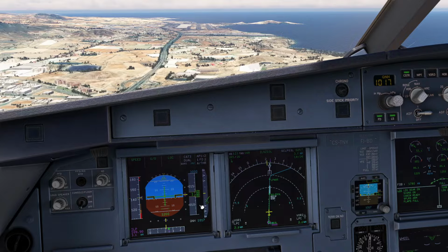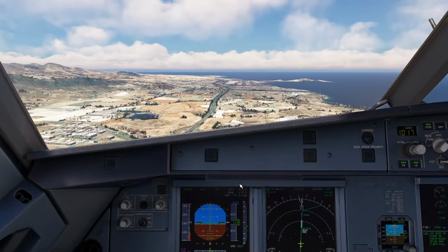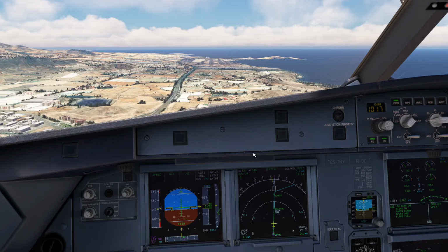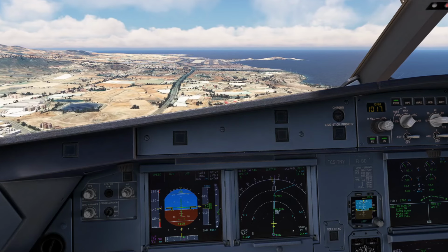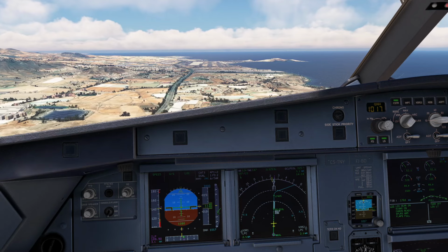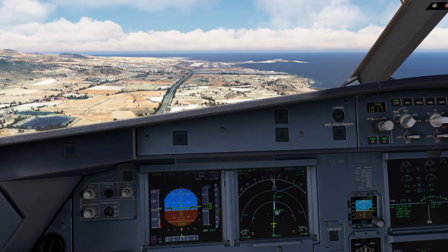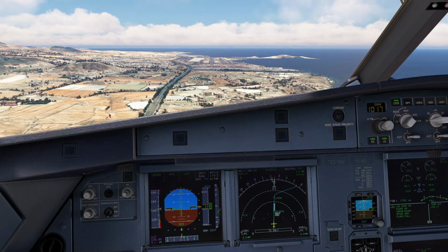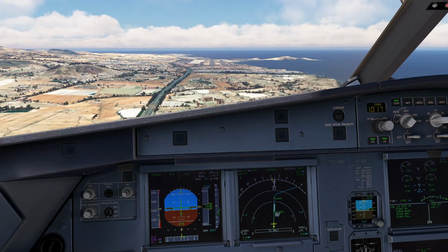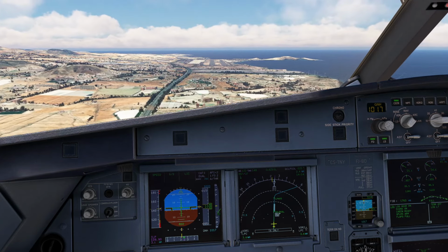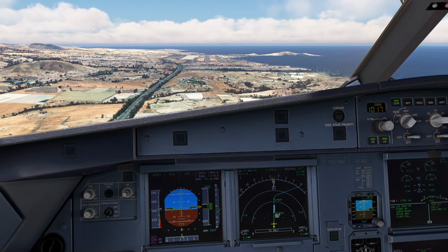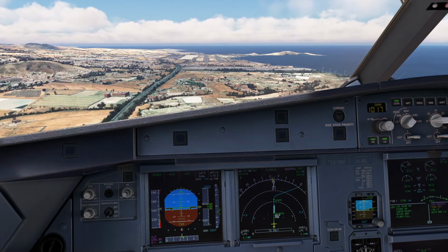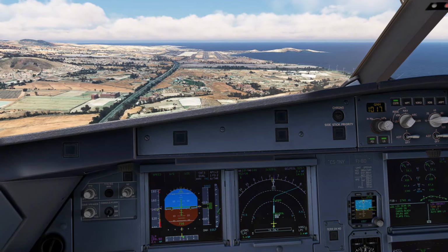Landing checklist completed, and it was a sample of a decelerated approach, where you continue at higher speed. If you do not have any limitation or constraint, you can continue higher a little bit, but today we had 1000 passed. We are stabilized on approach, and everything is about the decelerated approach as the same procedure that we followed today.